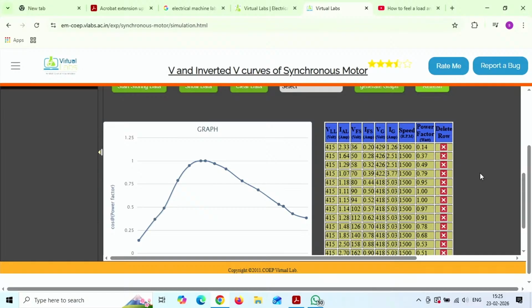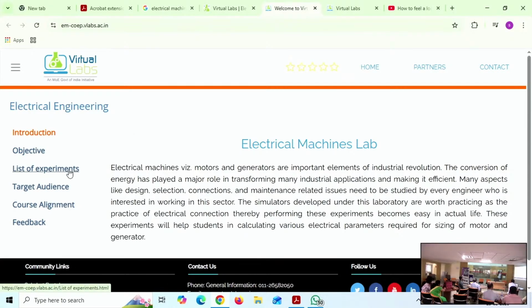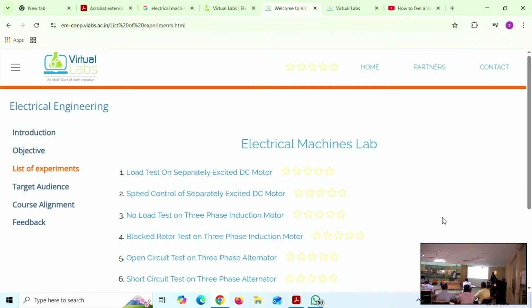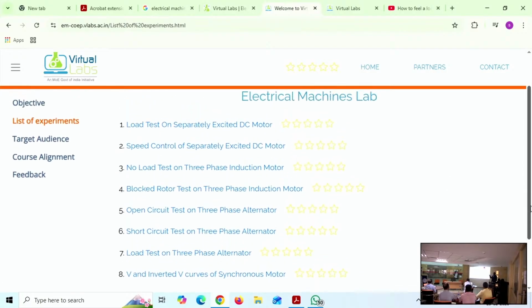Next, the single phase induction motor equivalent circuit again. Three phase induction motor principle is separate. Single phase induction motor working is separate. Here, single phase induction motors are not self-starting. If you observe, we make them rotate by means of splitting the phase. By means of splitting, we have such experiments also here.